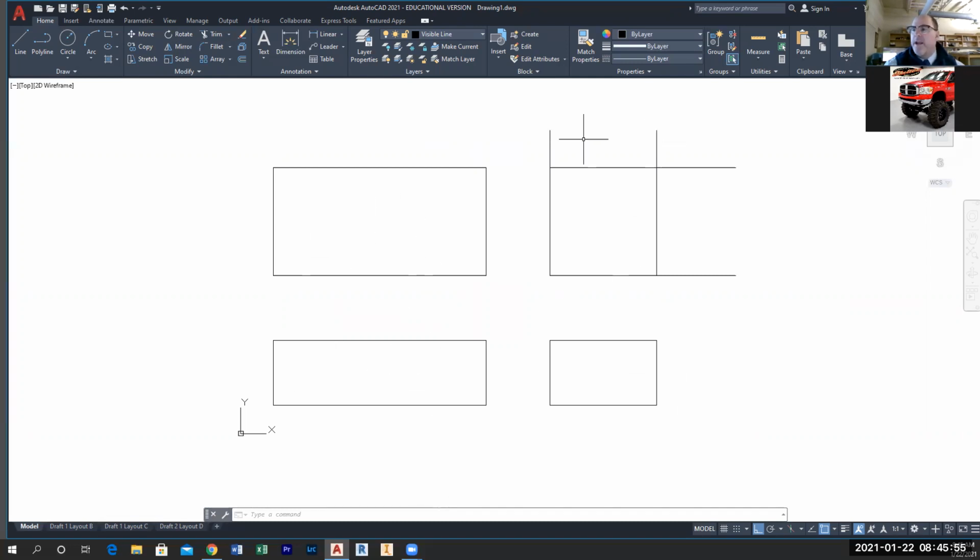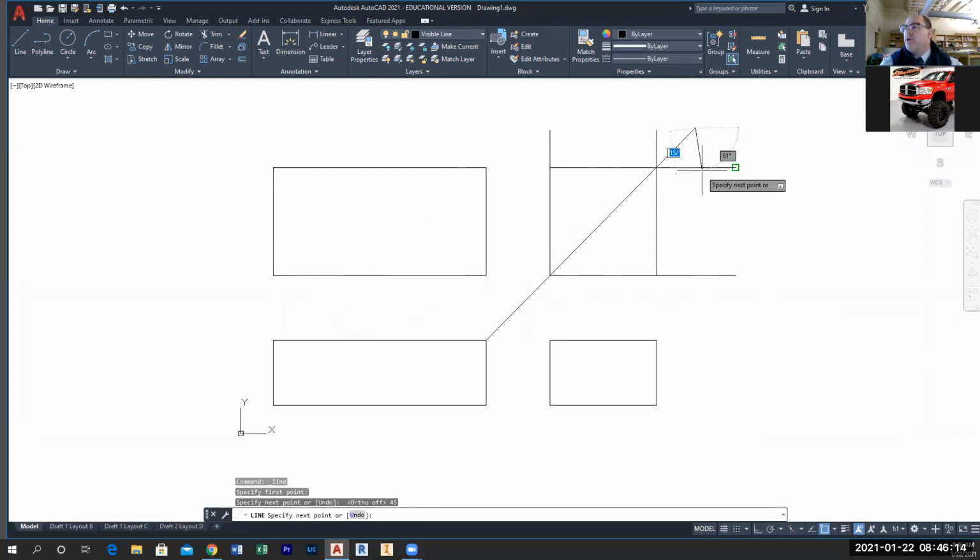Now this right here, if I were going to draw an angle and transfer over, if I was doing this mechanically on a board with a T-square and a triangle, if I drew a line up here at a 45-degree angle, let me just go 45, tab, 45, enter. You notice that the edge of that 45-degree angle goes to the edge here.